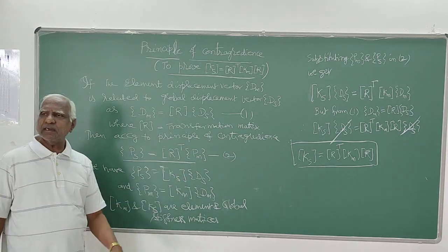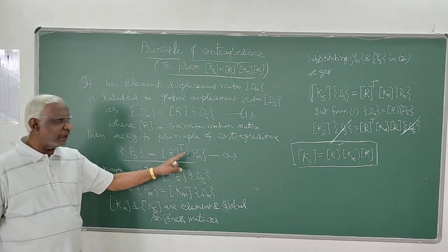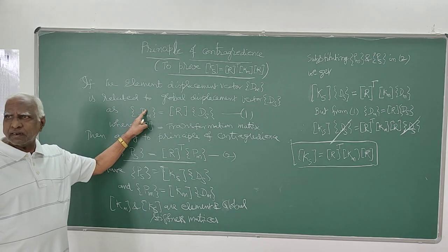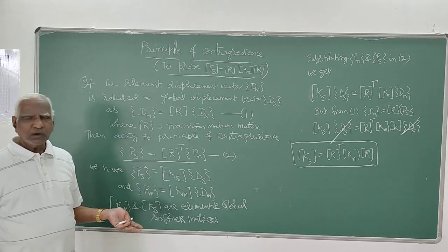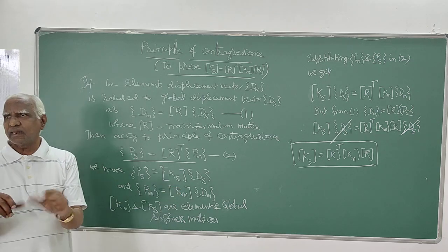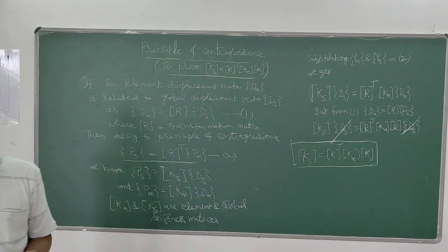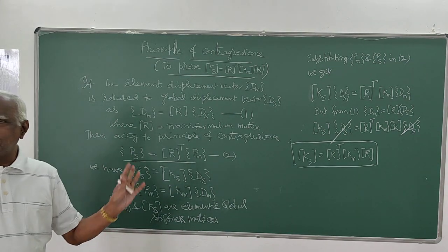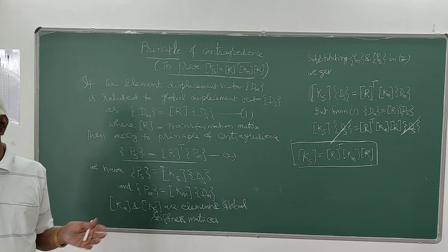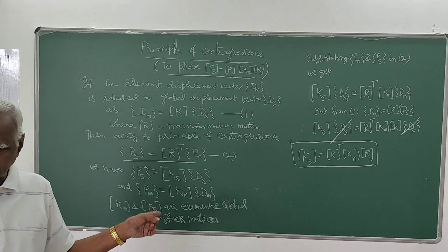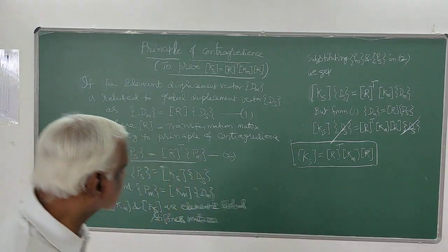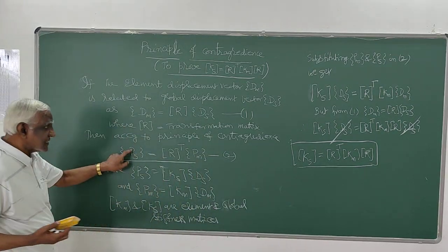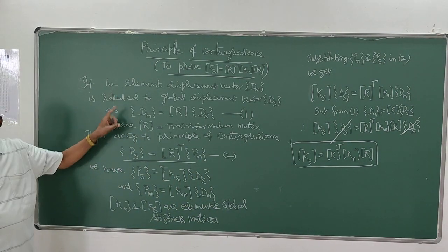Then once displacement is evaluated in global coordinates, the corresponding displacement in local coordinates you can determine. Then, knowing the member stiffness matrix, you can evaluate the internal forces. In just 3 steps, you can finish off the evaluation of the problem. So, next, how to derive this principle?